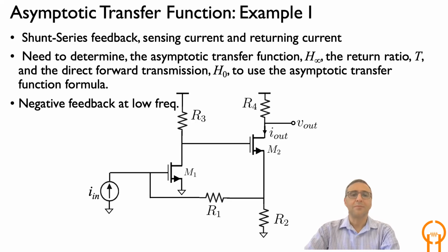So in this example, consider that the gate of M1 goes up, and the voltage goes up. The voltage of the drain, because it's an inverting stage, is going to go down, which is the gate of M2. That voltage going down is going to push the source down, because from that perspective, it looks like a source follower. And that would push that voltage going down on the right-hand side of R1, which will pull down the voltage on the left-hand side of R1, which is the gate of M1. So you can see that's negative feedback.